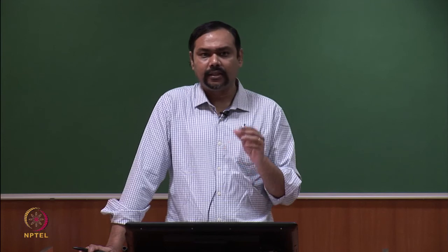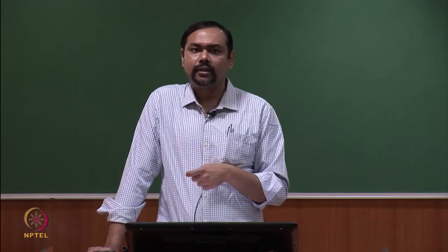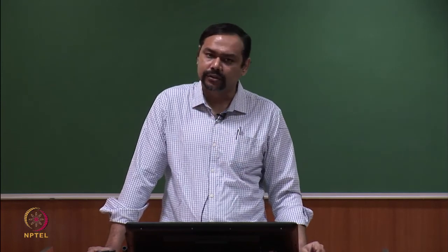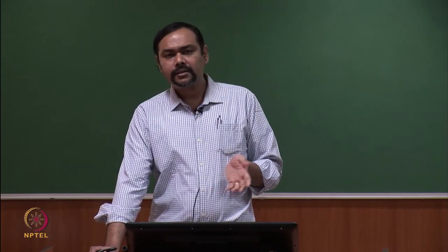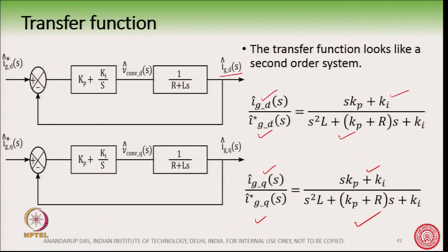When we model the VSC, what we found is that everything is fine. There is a D axis circuit and there is a Q axis circuit, but they have a cross coupling between them. The cross coupling term degrades the performance of the VSC. So, in the controller we apply a feed forward term so as to cancel the effect of this cross coupling term. And once this perfect cancellation happens, the grid connected VSC with an L filter behaves like this system here.